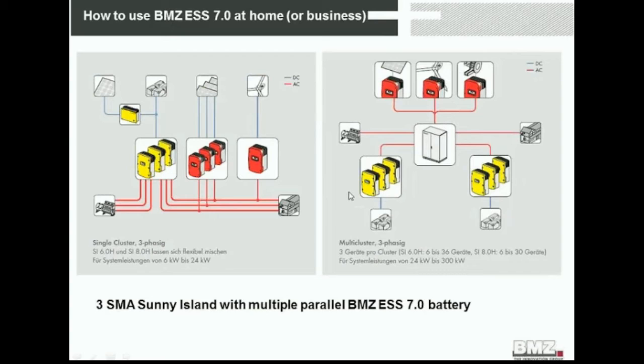This Sunny Island is available from 3 kilowatts power needed up to 8 kilowatts in single phase, and in three phase, I think up to 33 kilowatts. But that can be found in SMA data sheets or SMA training. As you know, I'm not an employee of SMA.